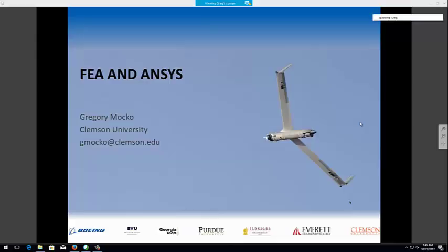These are really important. We had a student a couple of years ago attempt a very complex finite element model. It was a tube with a load on the end, and the student never pinned it down from moving in space. So he could never figure out why his computer kept crashing. Well, the problem is he didn't have the right model created.